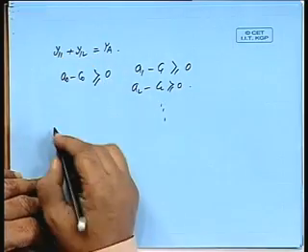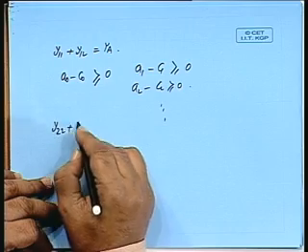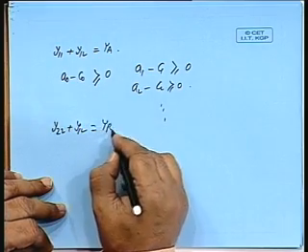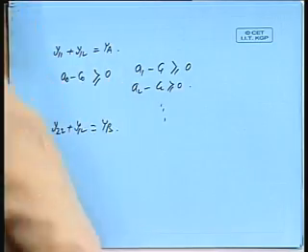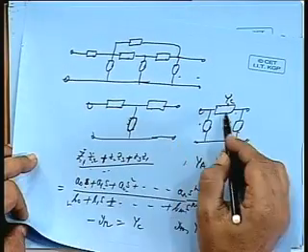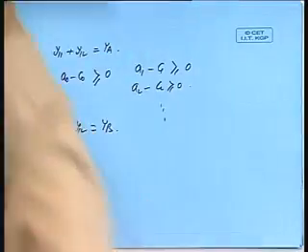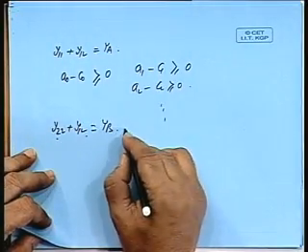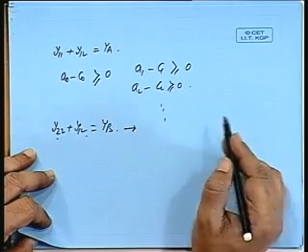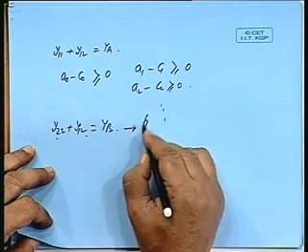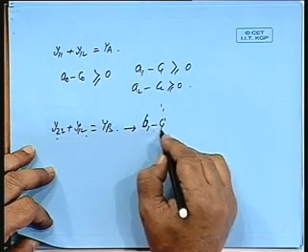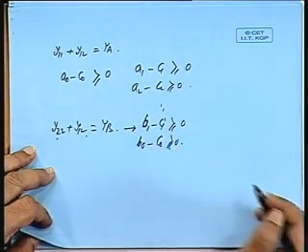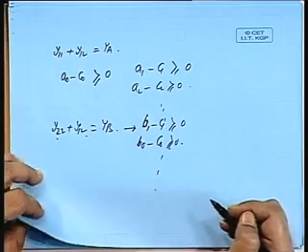Similarly, by the same logic, y22 plus y12 is how much? Yb, and that also we discussed after repeated reductions. Ya, Yb, Yc must have all positive coefficients in the numerator. So, y22 plus y12 also must be having numerator coefficients greater than or equal to 0. So, b1 minus c1 is greater than or equal to 0, b0 minus c0 is greater than or equal to 0, and so on. All right.